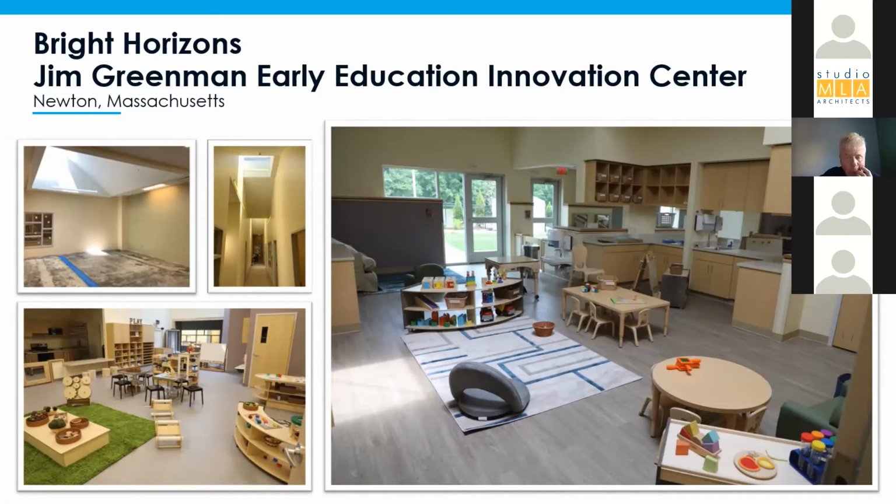The image to the right shows actually an instance where we had to be cautious where our openings to the outside would go. So the portion of the wall here that you see in the back wasn't allowed to be penetrated just anywhere that we wanted to. We really had to be cautious about the location for those openings because it would damage the structural integrity of the building if we came within a certain distance of any columns along the perimeter. So we wanted to provide as much natural light along the exterior as we could. So we opened the foundation walls where possible, but then we tried continuing skylights or side lights wherever the space allowed for it above that foundation wall.